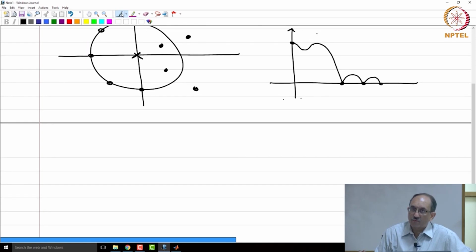So, in the case of pole-zero filters, poles contribute to passband behavior, zeros contribute to stopband behavior, and zeros contributing to stopband behavior are zeros that are typically on the unit circle. For the FIR filter case, where you don't have poles to play with, passband and stopband behavior are governed by zeros. Passband behavior is governed by zeros off the unit circle, and as before, stopband behavior is governed by zeros on the unit circle.